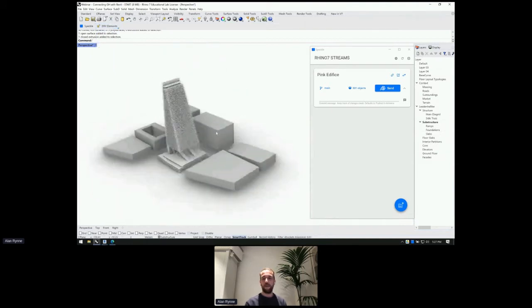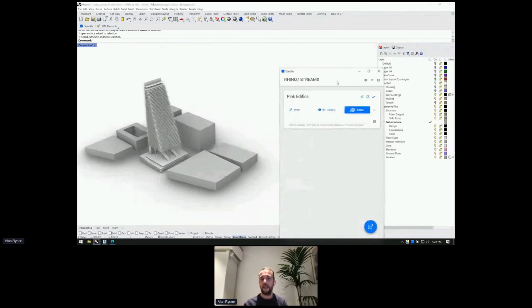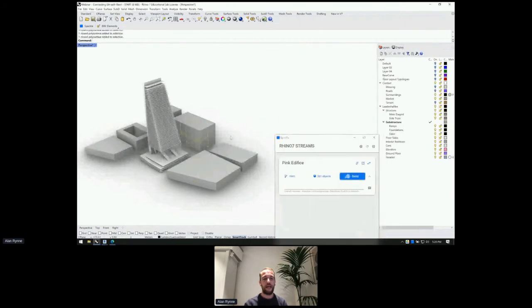Let's say I want to select, let me see if I can grab this layer and pull it out. There you go. Let's say I want to select all of the massing buildings that I have around and specify that I want them to be strictly direct shapes. So we can grab the layer, select objects, and once those objects are selected, I can select the direct shape command, and then it will ask me to select some geometry. So I'm going to select the surroundings and then press enter.